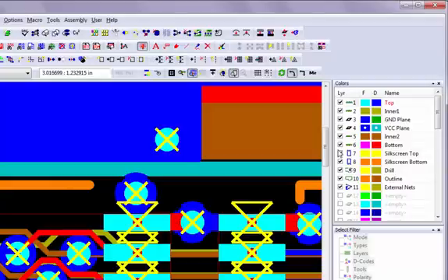For future reference, pressing the Escape key is how you tell VisualCAM to stop running a command anytime during the process. If you have a specific set of layer colors you would like to use for all of your designs, we have a macro called Set Layer Colors that allows you to choose your colors and add this macro to the OnStartup macro so that all job layer colors will be set the same every time. See the video in this series for detailed information on how to set this up.